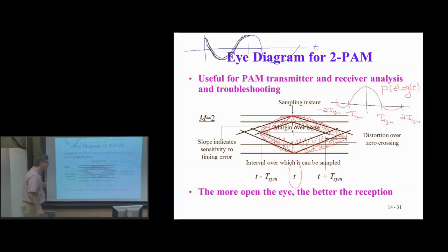Now, you can also see other impairments like the change in sampling in the symbol time. If you're off in the symbol time, then what will happen is you'll cut short the 0 crossing, and that will map into an eye diagram. Instead of getting this in the eye diagram, you'll miss this point here, and so this will come, let's say, here instead of 0, and the rest of it will come down. And the more the miss, this eye will start closing.